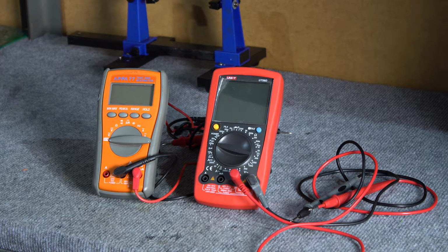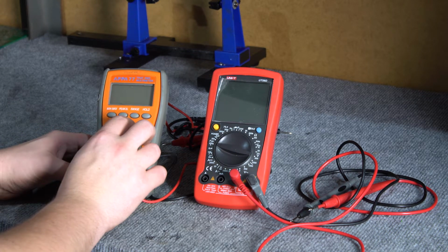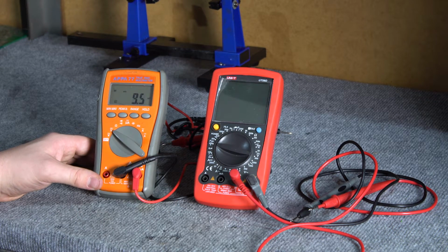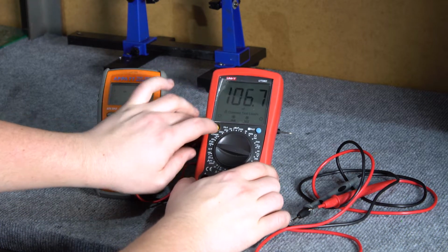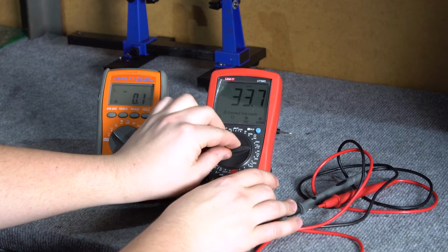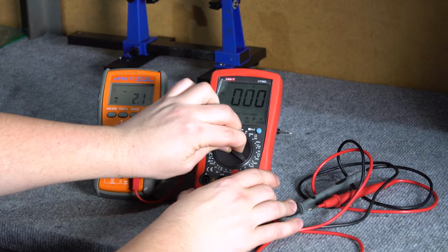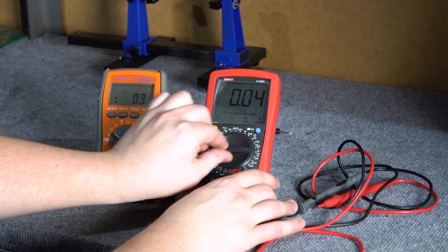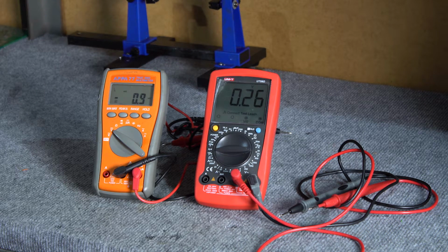Before we discuss the most important features of the multimeters, we have to know how to incorporate them safely. Let us start with the voltage meter. The voltmeter, as the name suggests, measures voltage in volts. As we remember, the voltage occurs between 2 points, so the voltmeter is always plugged in parallel to the tested system or element. The voltmeter section in the measured meter should have the highest possible internal resistance, so large that the parallel connection of the voltmeter's resistance to the system does not cause a noticeable increase in the power consumption.